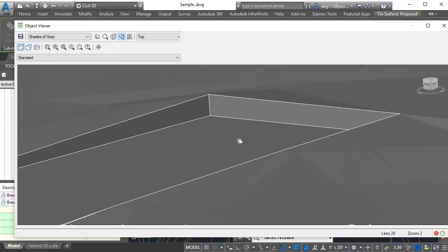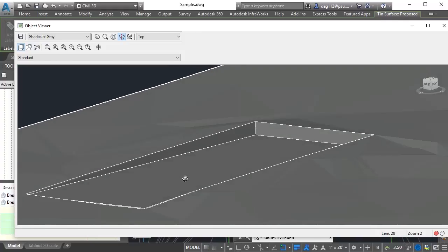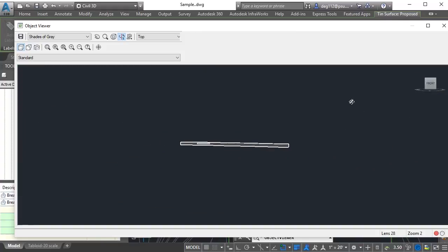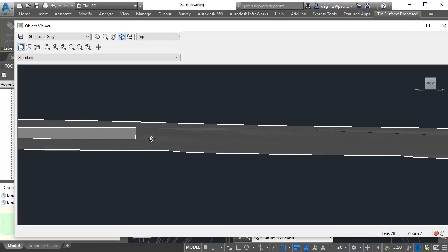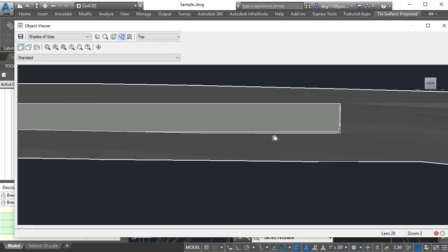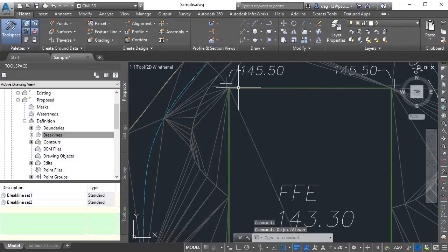That's a very clean wall that I just created, because I'm now using a feature line that runs along that surface as we defined it, including hitting those contours into our spots, including creating a flat area. Actually, if I look at the front, we should be able to see a flat area where our door would be. Right there. It's a nice flat area right there where the door is. Works really well.